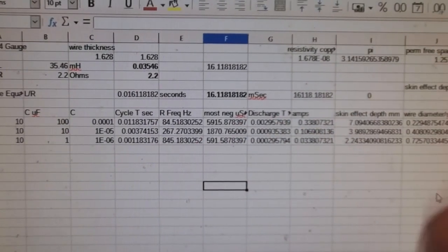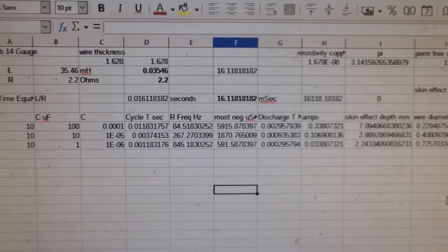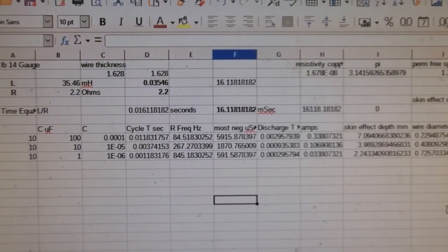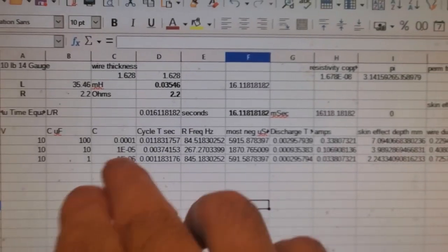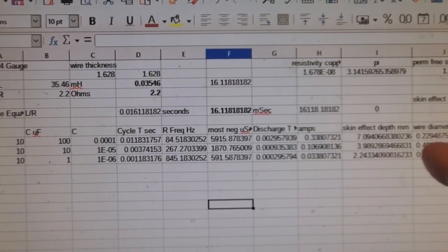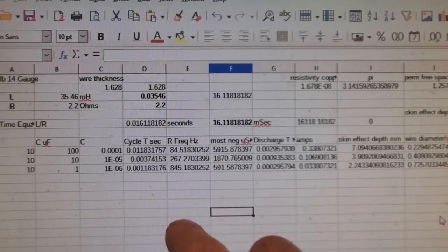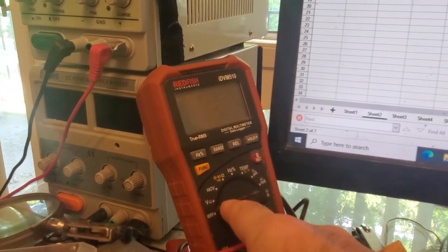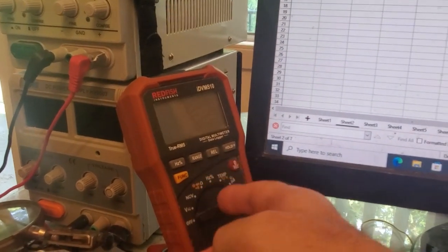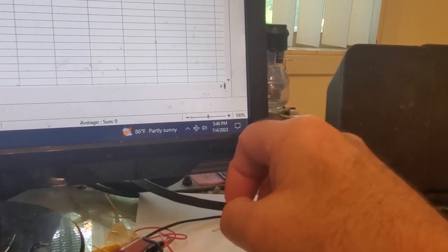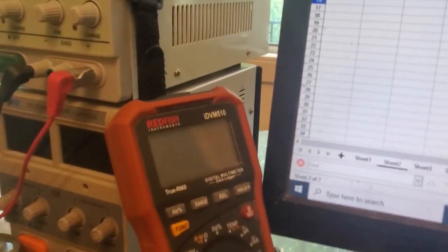Well, what my thinking is that, we know per Ohm's law... Sorry, I had to. Ohm was a German physicist, and he came up with the famous V equals IR. And so V equals IR, and I don't know because I can't measure it, but I can discern it, that there's a 10 mega ohm resistor that's kind of standard in this meter. So if you add another 10 mega ohms, since V equals IR, and R is doubled, all your readings will be halved. But I think that's the only problem.